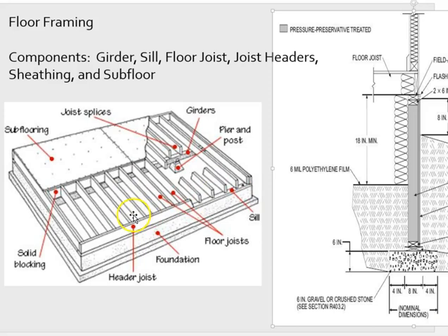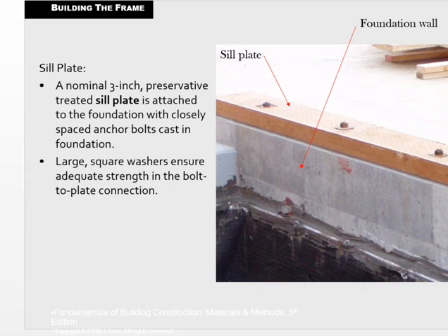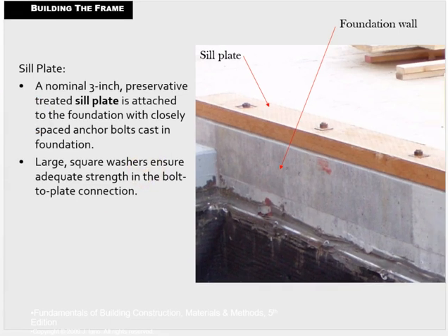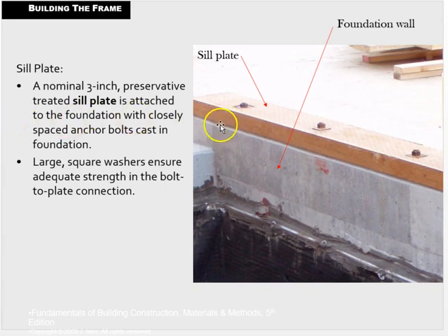Okay, moving on. I'm going to skip this detail. And moving on with my frame again. There we are. Okay, so the sill plate here in this situation is slab on grade. Well, actually I shouldn't say that. I can't be certain. This is kind of washed out. This could be a foundation wall, and that could be sheathing. It appears to be more like a slab on grade to me, but I can't be certain.